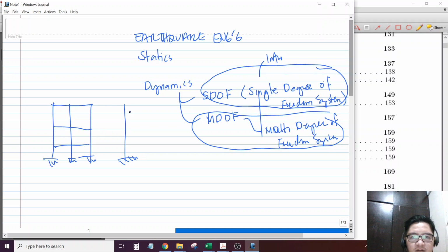Degree, you should be familiar with this now because in structural analysis you talk about degrees of freedom. So, we lump our mass here. This is the mass. Of course, every building has mass. Then you assume this whole structure is a cantilever column with mass. And this structure also has, besides mass, K, stiffness. Basically, that's a single degree of freedom system.